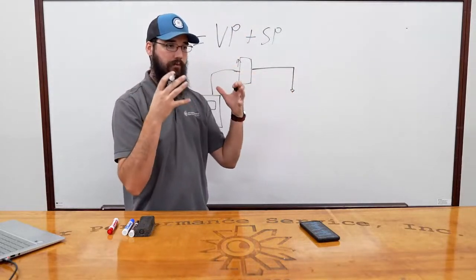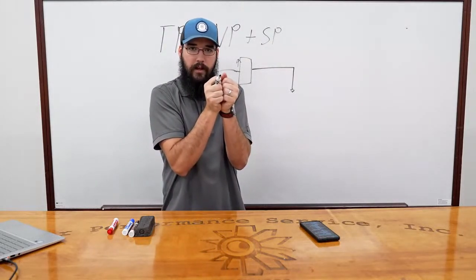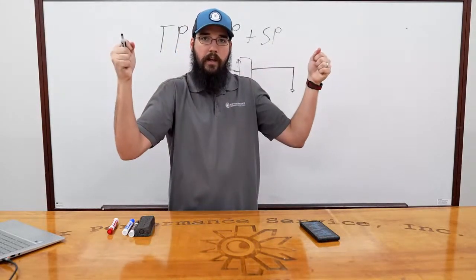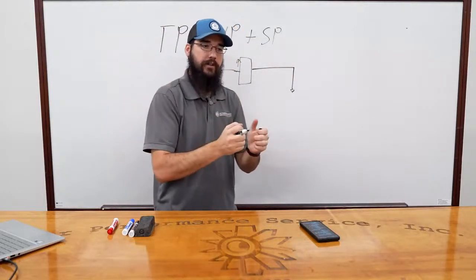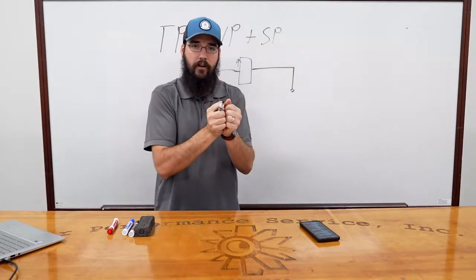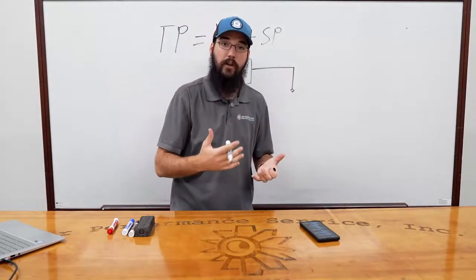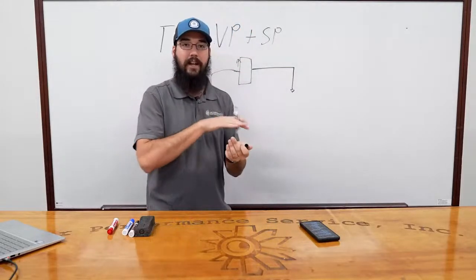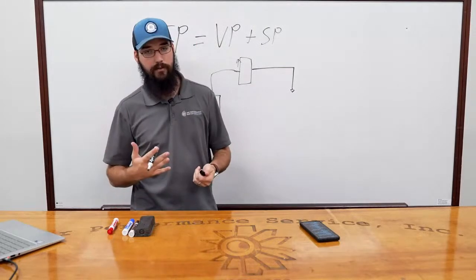When you think of refrigerant pressure, the refrigerant is balled up in a confined space, and it's trying to push out. And it's doing the same thing inside of the ductwork. So your static pressure is the pressure of the air trying to push out or pull in if it's in regards to return. So a return side would have a negative pressure, where the supply side would have a positive pressure.